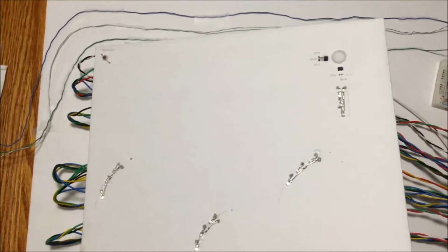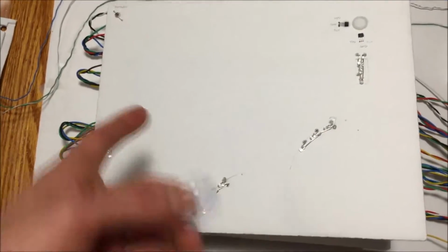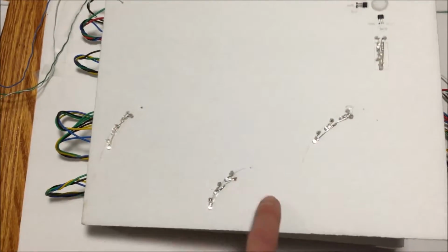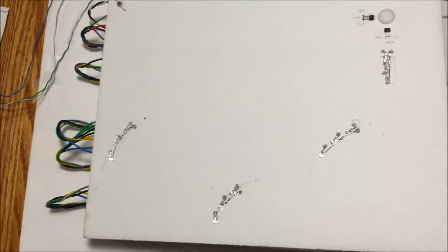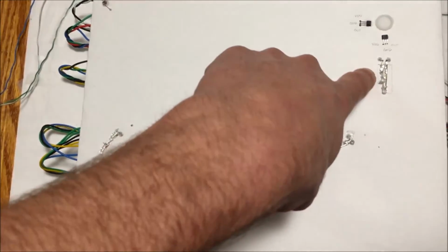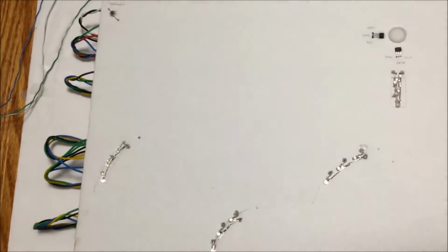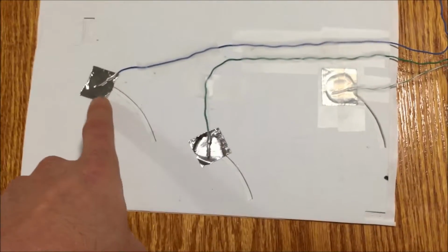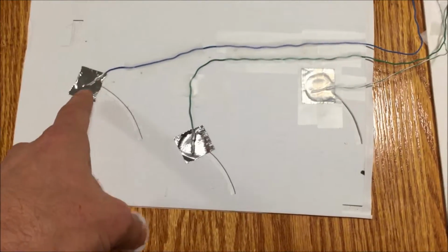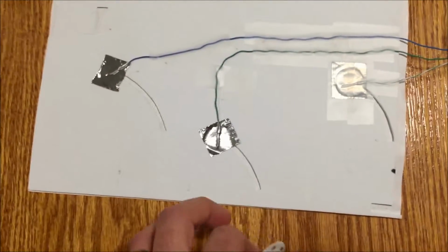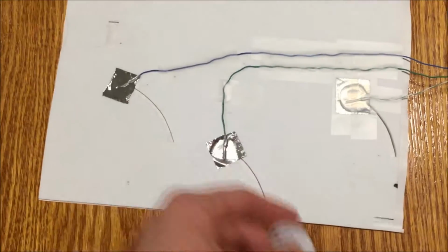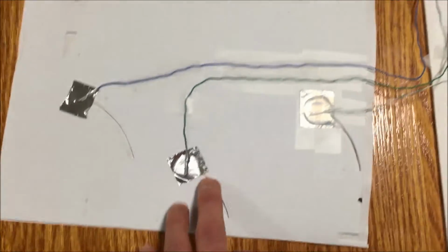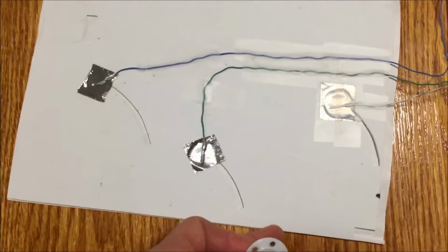So this is the artwork removed from the seal page, just to give a better idea of how it's working underneath the hood. Each of these sets of 3 LEDs is 1 leak. This 4th set of 3 LEDs is the water supply, and you can see the electrodes on the back side of the artwork. Those are what are detected by the MPR121 and communicate back to the board whether one of these is touched or not. And again, this is a capacitive sensor detected through the paper of the page.